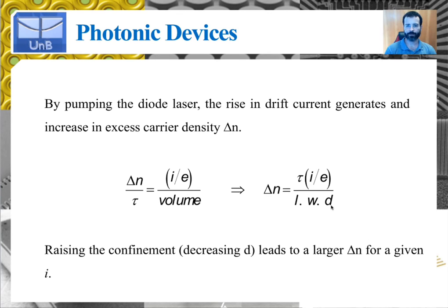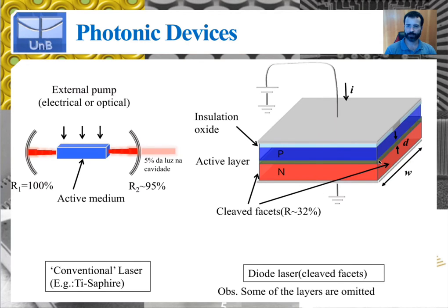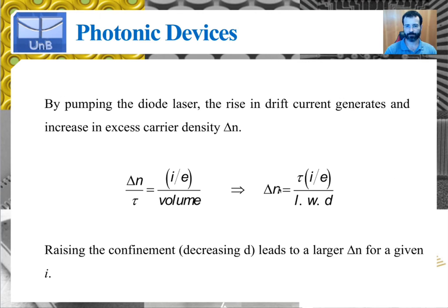So again, by using double heterostructures, for example, or similar structures, you can reduce the volume of the active region by, for example, reducing the thickness of the middle layer when you're fabricating the device and depositing or growing all of the layers. Therefore you can get more efficient devices by tailoring the current that you need in order to obtain a given excess carrier concentration that is desired.